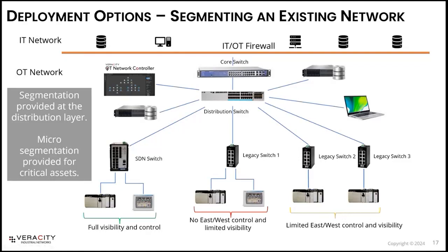It's the most common switch we see out on plant floors as far as rack mounted ones. And you can actually just activate it into OpenFlow mode. You put a controller in your virtualization stack, talk to that, and you have automatically segmented your network very, very easily. Everything that passes through this is under the same types of controls that I showed in the previous slides.